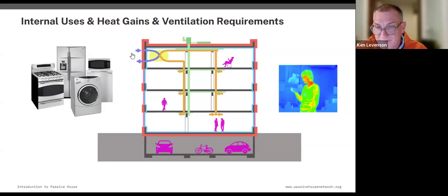So the key thing, and this slide will sort of do it, is that you've got the heat exchange happening near the exterior of the building. That ductwork that goes from the unit to the exterior is effectively outside, because the air that's coming out of the unit is outside air effectively, right? It's back at the outside conditions. And the air coming in has not been exchanged yet. So those ducts need to be very well insulated and sealed against potential for condensation.